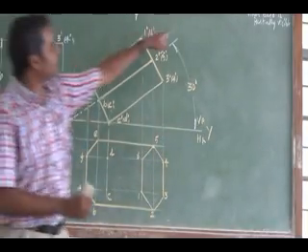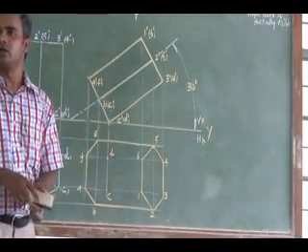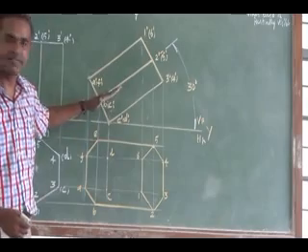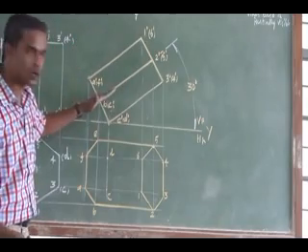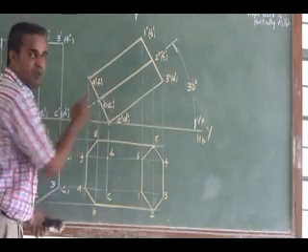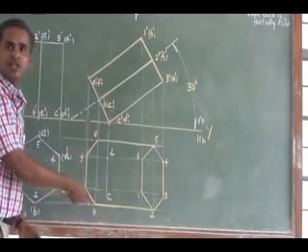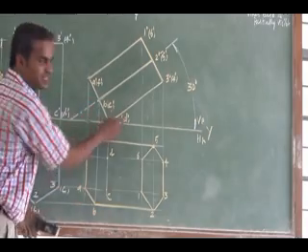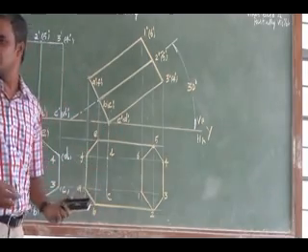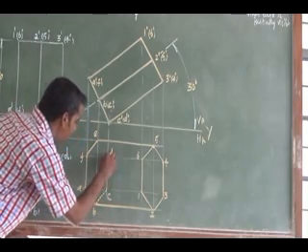Right. So you see the corresponding other base. This corresponding other base is partially visible. Partially visible in the sense this half is visible. The top half from the axis is visible, below the axis is hidden. From the axis, the top half notations are AF, BE. Already it is on the boundary, so it is visible. The other half, BE, CD, that is hidden. It is a partially visible base, so that is hidden. You have to join it with a hidden line.